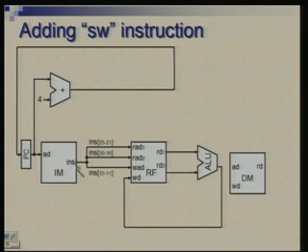Unlike instruction memory, this will have data input as well, and that is actually the only difference. You have address, read port, write port. Okay. Well, actually strictly speaking, it will not be considered a 2-port memory, it will be considered a 1-port memory, because you either do read or write, there is a single address, all right, and we will define control signals which will ensure that either you perform read or write. Okay. So, it is a single port memory, but it can do read or write, whereas this is a 3-port memory, 2 read ports and 1 write port. This one has a single read write port.